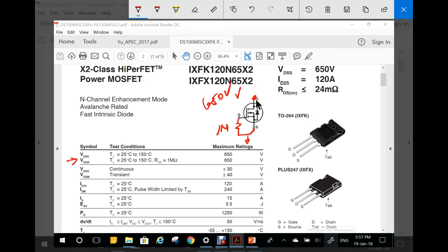Now, if there is a sort of conduction path between drain and gate, this may turn on the transistor. So by these parameters, we understand that we have a safe situation in which even high impedance here will not be affected by the voltage imposed, or the electric field between the drain and the gate. Okay, so that's for the VDSS.